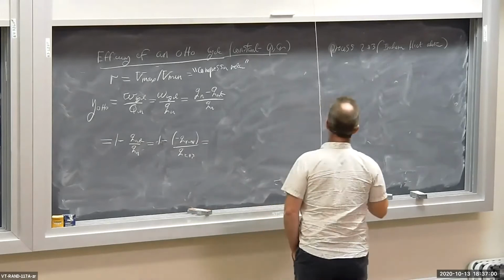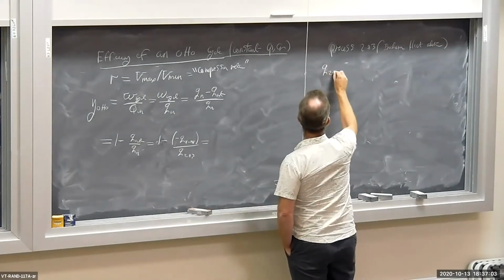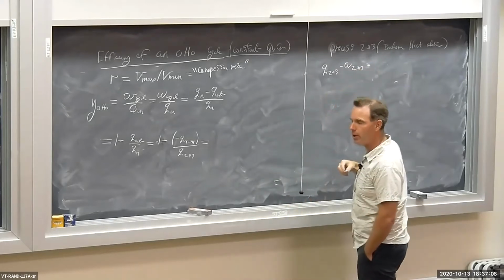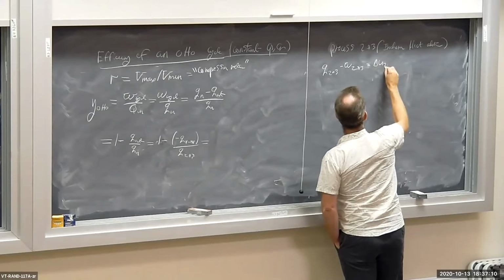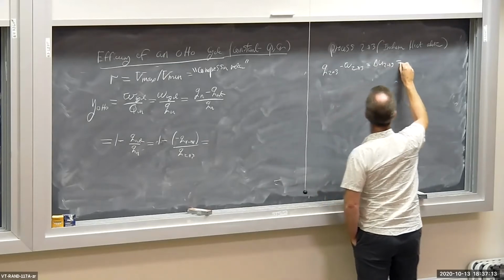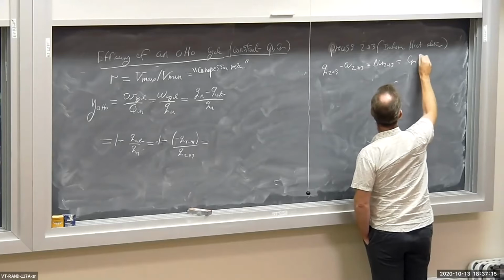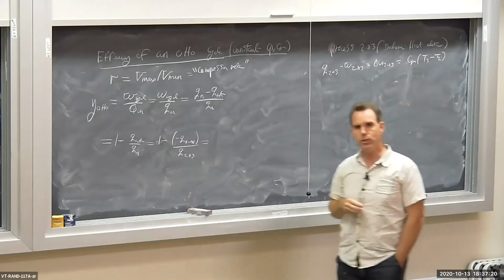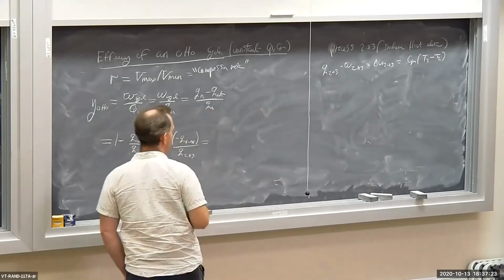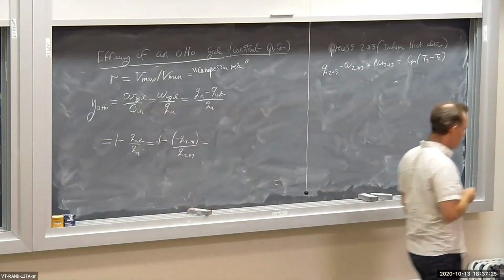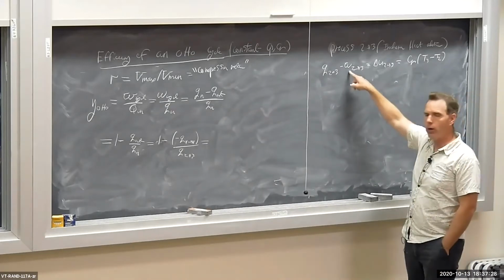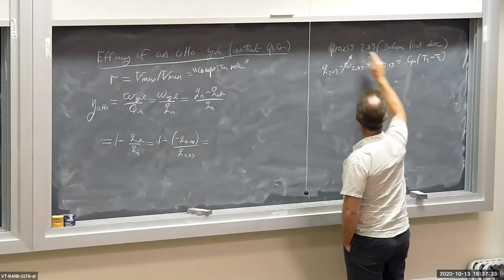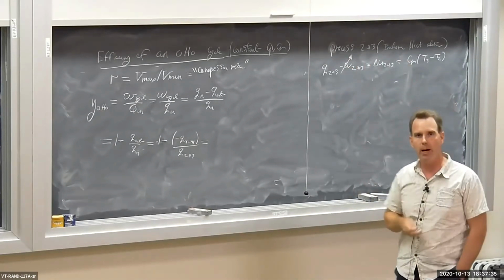Applying the energy balance, we have q 2 to 3 minus w 2 to 3 is equal to delta u 2 to 3. And if we assume constant specific heats, that's going to be Cv times T3 minus T2. Now, if it's an isochoric process, what's the boundary work? Remember, this is boundary work. If it's an isochoric process, constant volume, what's the boundary work? It is 0.